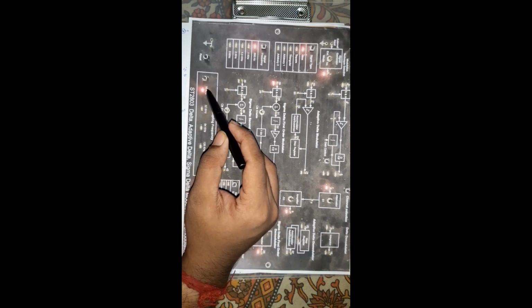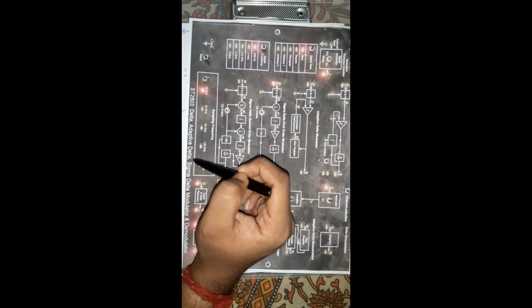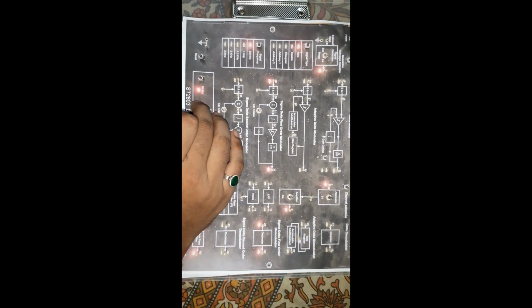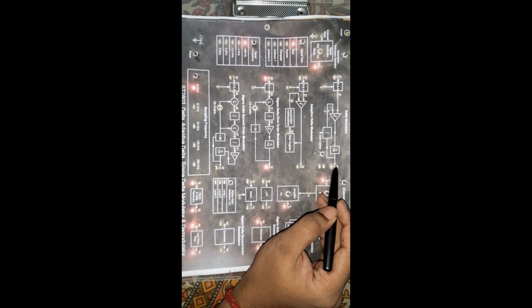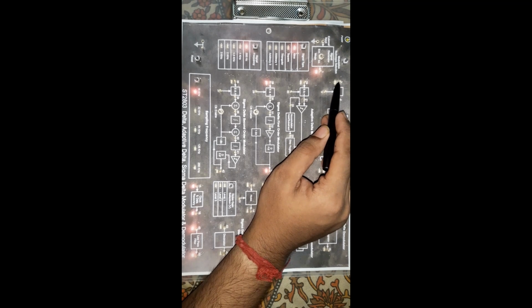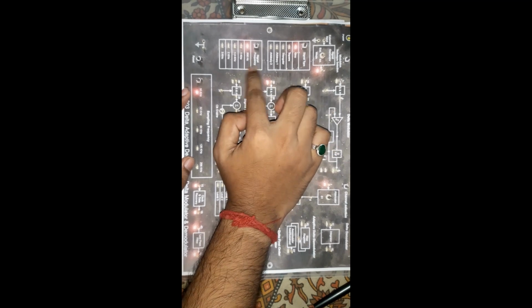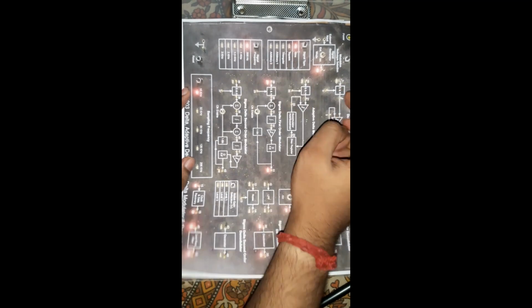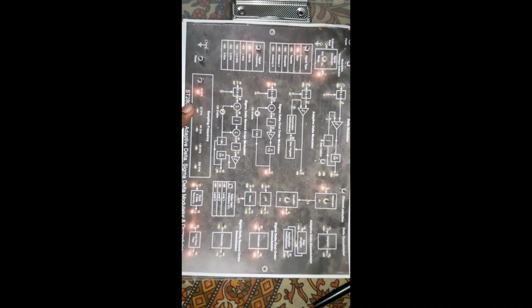That means we have just selected the lower sampling frequency, that is 16 kilohertz, and by pushing this button you can switch between several sampling frequencies. By default 16 kilohertz has been selected, which is more than enough. Okay, and from here, see, now the vital step is coming. At the input of the sample and hold circuit, you will find the signal that is provided. The input sinusoidal signal is fed here, and it looks like this.